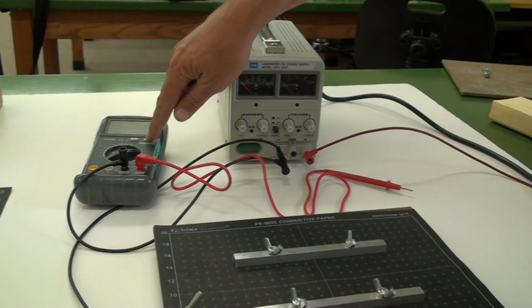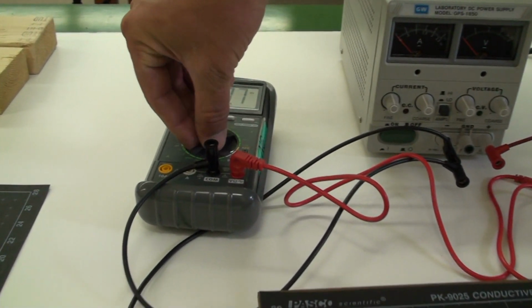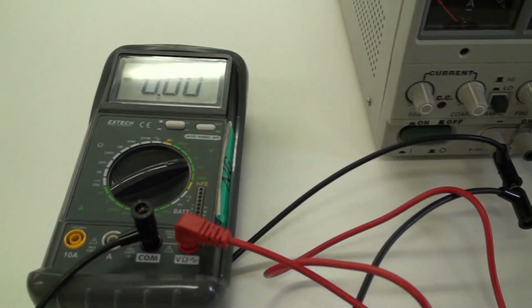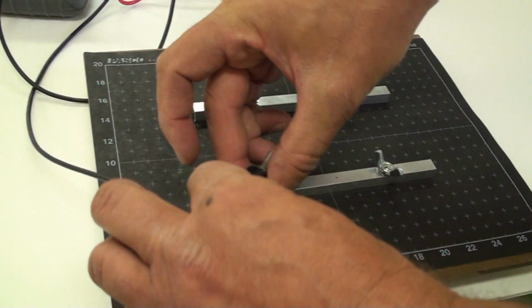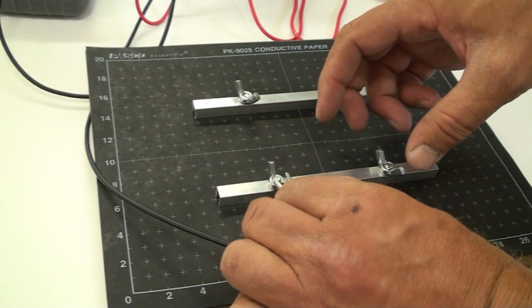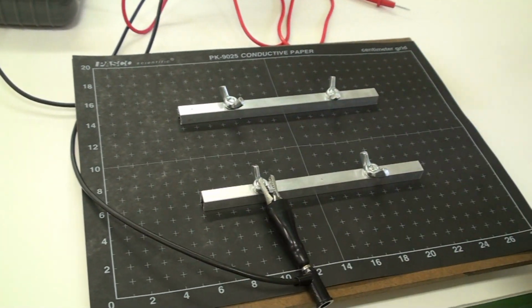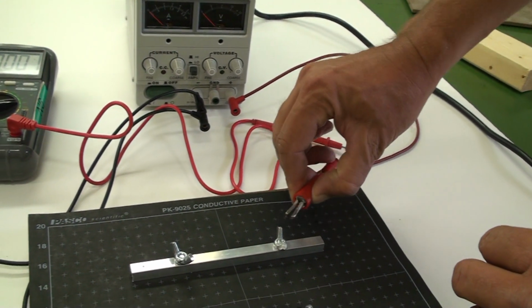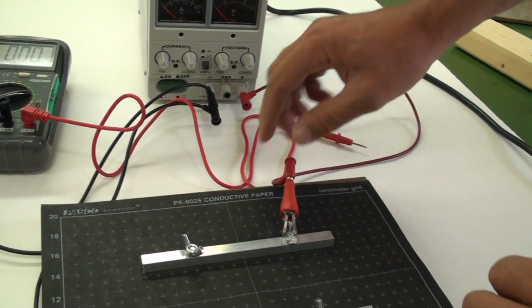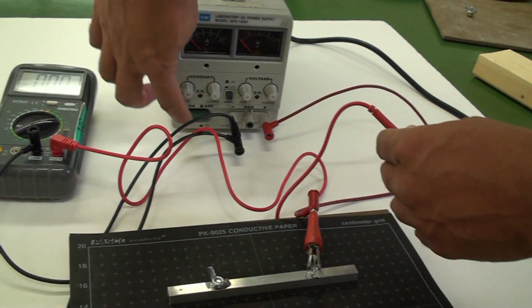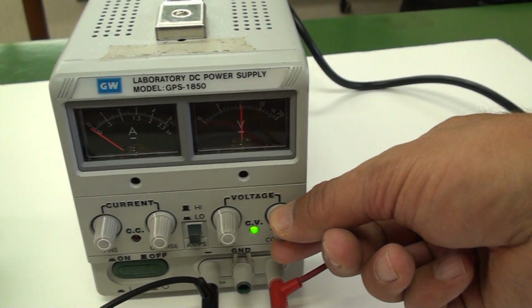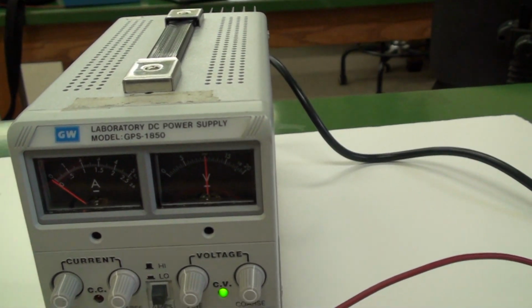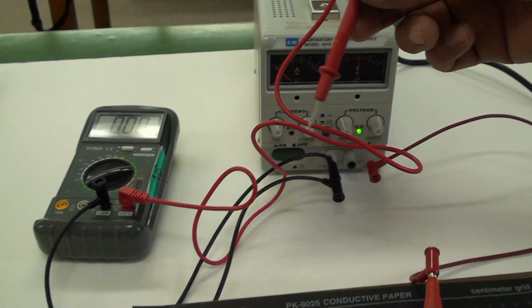led to later problems. With our 2 conducting strips screwed firmly in place, we connect the common input of the voltmeter to one of the strips using the alligator clip. Then connect the high voltage output of the voltage source to the other strip. Turn on the voltage source and adjust the output to approximately 10 volts using the coarse adjustment knob.